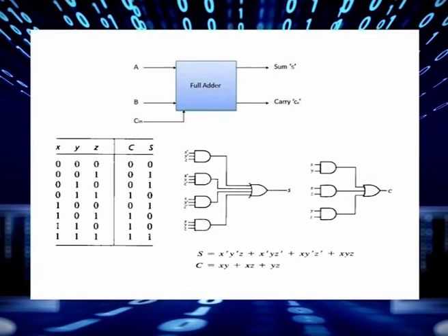By looking at the truth table, we can see that using full adder we can add the two inputs as well as the carry from the previous stage and will give the output as C and S. Further, we can conclude that we can develop full adder circuit by using AND gates and OR gates.